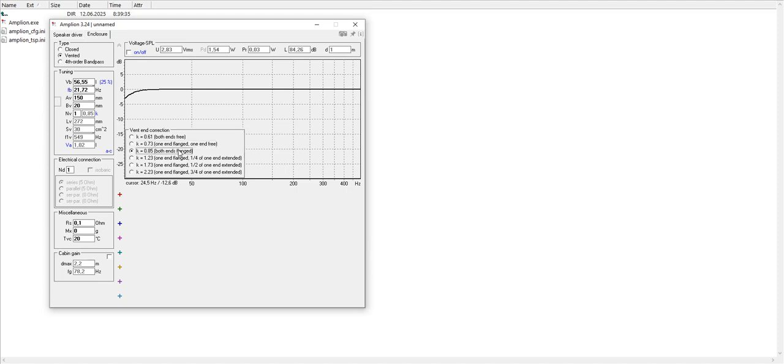If the vent is a rectangular slot at the very bottom of the box, then a large part of the air still acts as a loaded mass due to the extended walls. The K is approximately 1.73. A value of 2.23 applies to the very special case of a square vent having the same width as the internal width of the enclosure.